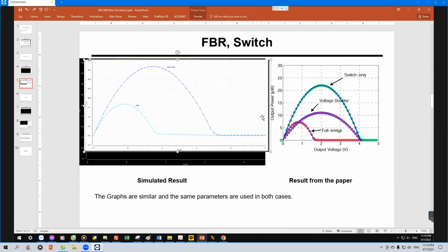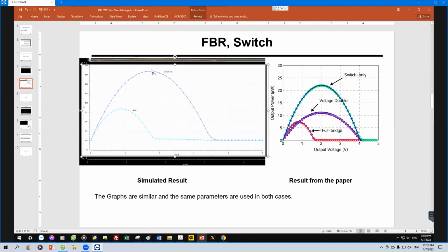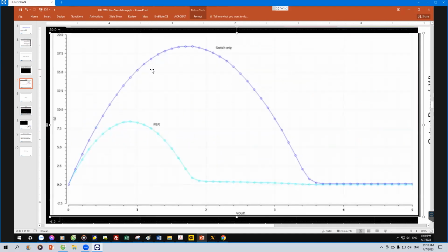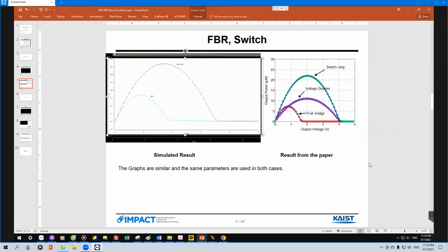It is 18%. It's not small. So we will say small when it is under 10%, right? It's around 20% different. So when you see a big difference over 10%, you should think why, right? So my assumption is that the diodes are working differently in the simulation. So next time you should include the equation here.